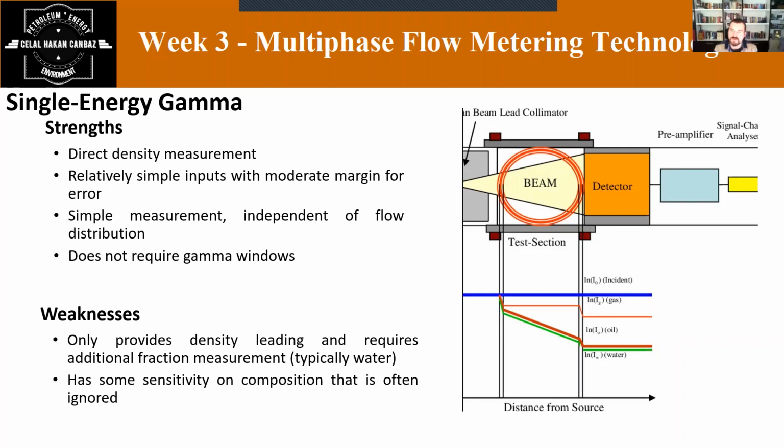It uses a nuclear source, and from this nuclear source the gamma ray photons pass through to your line. As I mentioned, it becomes part of your line. Your flow is coming directly, and these gamma ray photons pass across the cross section of the line. What happens? It collides with the molecules of your flow, and according to that, it gives you a result.